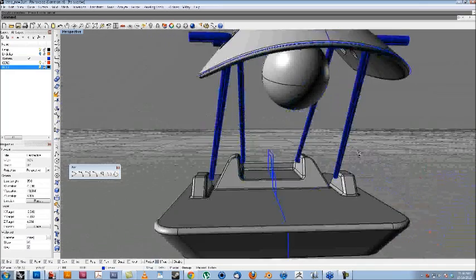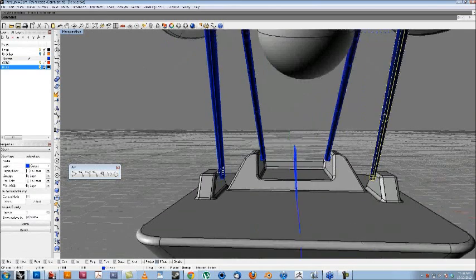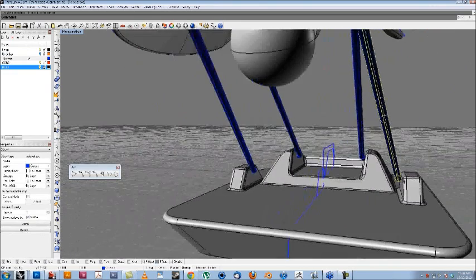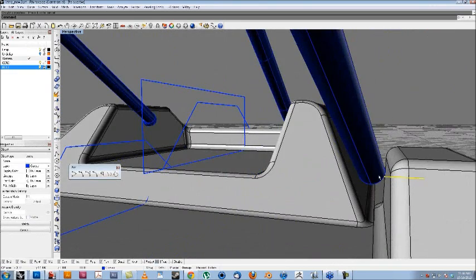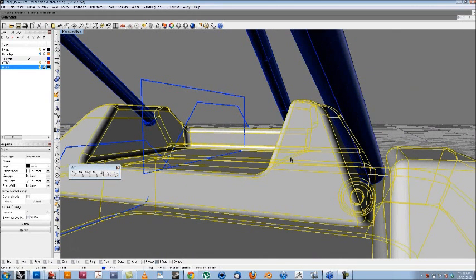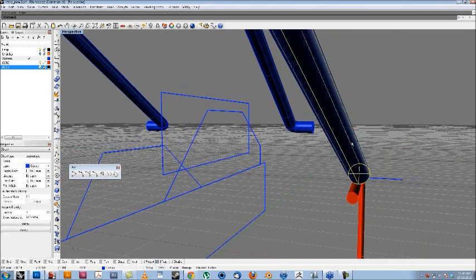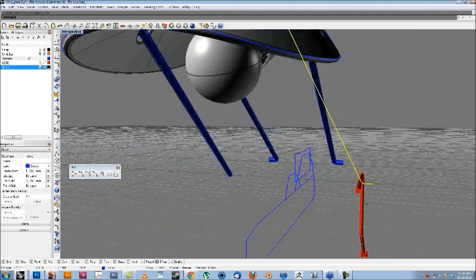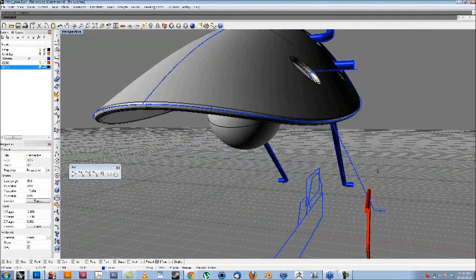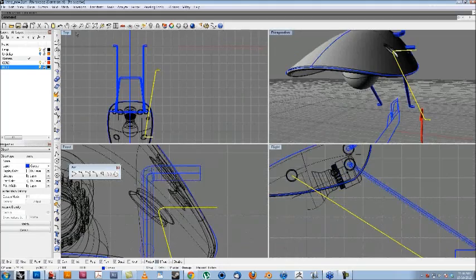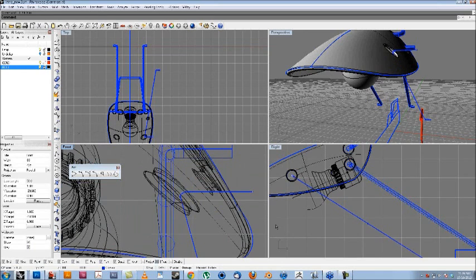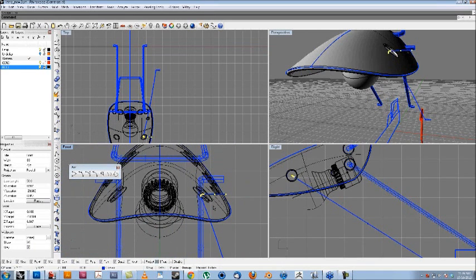The other thing I'm noticing here is I'm having a little bit of an issue where the curve that created this pipe didn't actually pipe all the way, and that's probably because these didn't join. So I will go ahead and remove that and just make sure it's all joined up. And while I've got it here, I think I'll actually move it in slightly by turning on its points and just shift it over. Now I'm just hitting Alt right arrow, and that's nudging it into position.